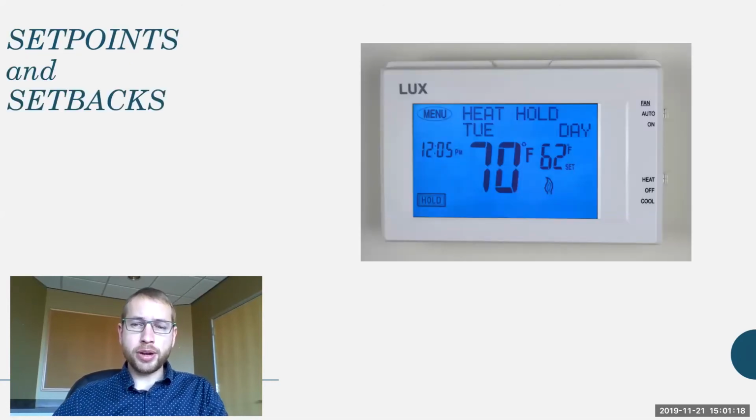All right, and so that's why set points and setbacks have a really big impact on energy usage, depending on how much reheat you're doing and how much airflow you have coming into the space. So pretty straightforward, programmable thermostats. They work great in theory. In practice, they often get overridden.